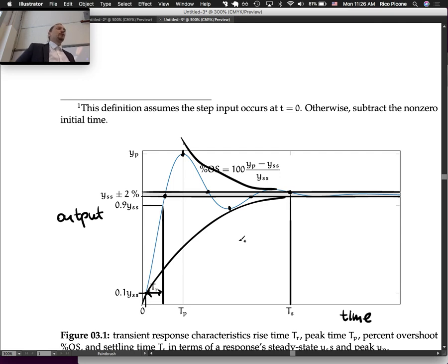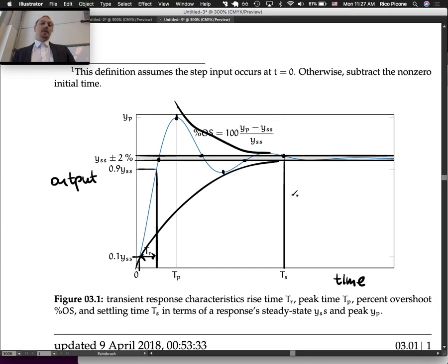Cool. So we're looking at a system that probably has a complex conjugate pair of poles that are stable, so they're in the left half plane and have negative real parts. And there may or may not be a zero in there. It's hard to tell from the step response. We could talk about non-minimum phase systems, but that's a little beyond this course. So this was there to demonstrate that even if this was a fourth order system being simulated, we can still define these parameters: the rise time, the settling time, etc.